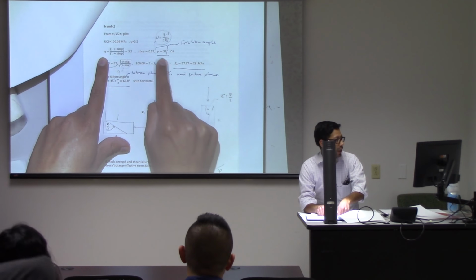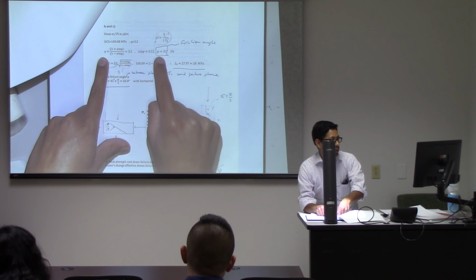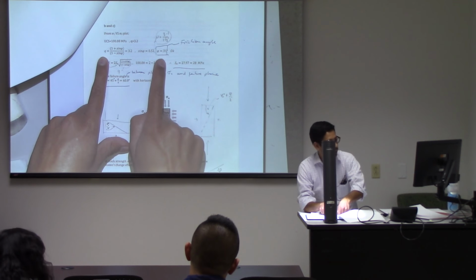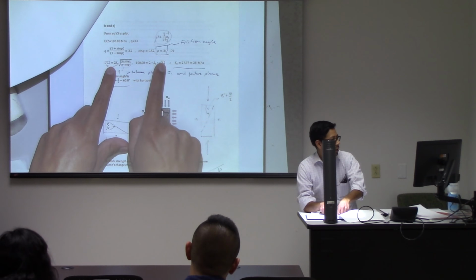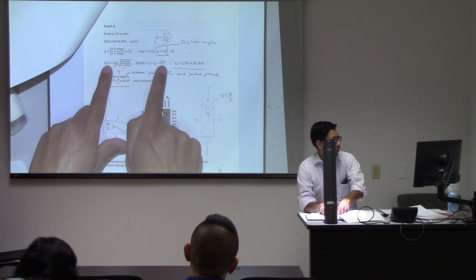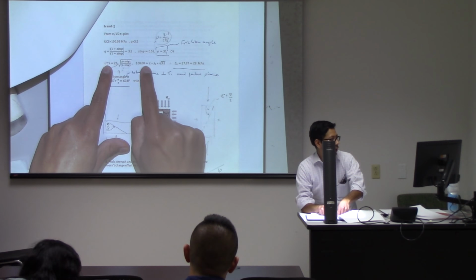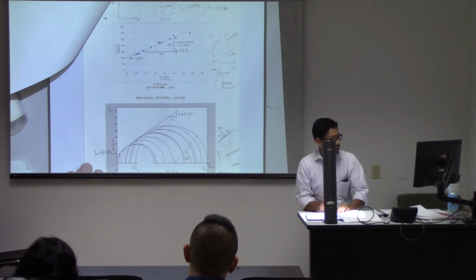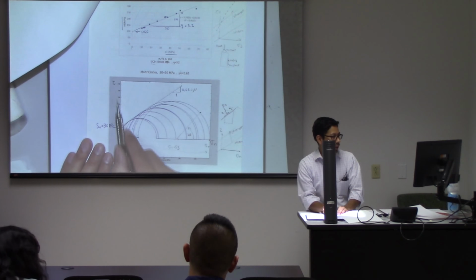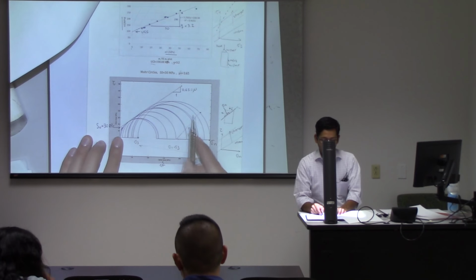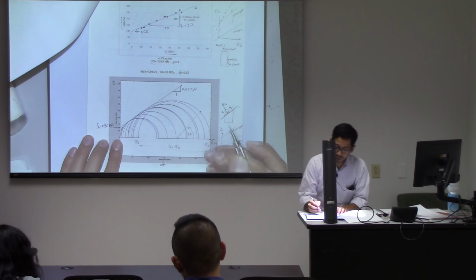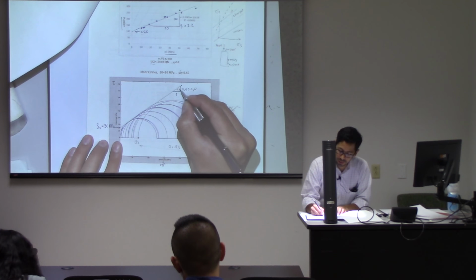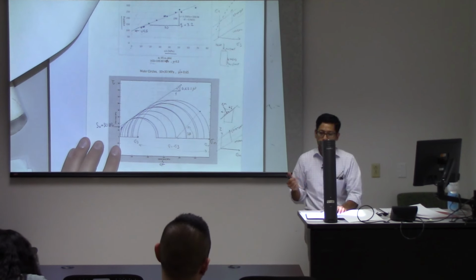If I know the friction coefficient, I can compute the friction angle. And if I know UCS and Q, or the friction angle, I can compute the cohesive strength. The cohesive strength is the intercept of this line in a tau sigma m plot, and the friction coefficient is the tangent of the friction angle of this line.